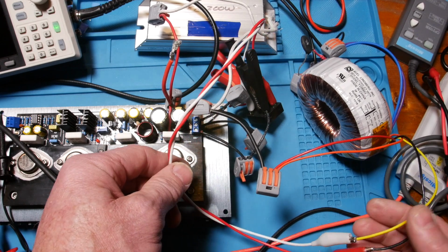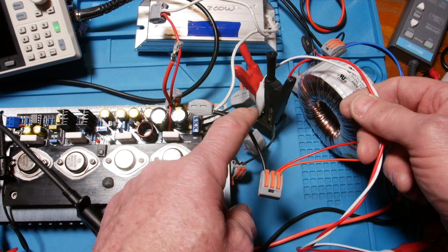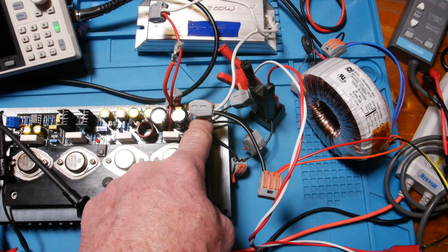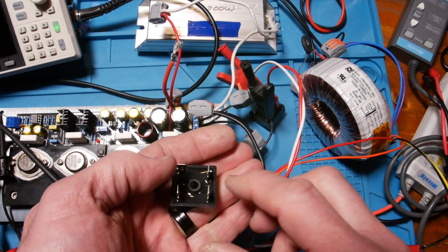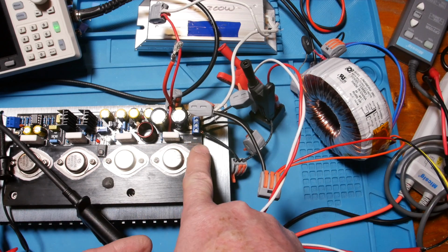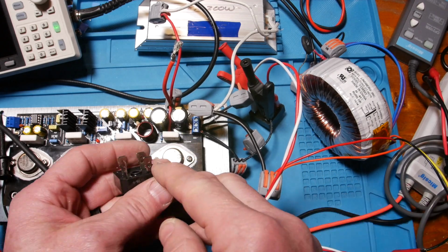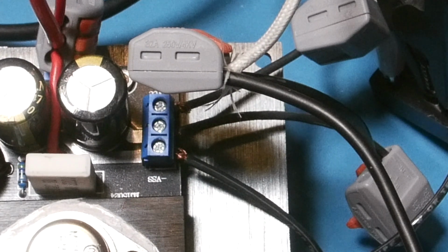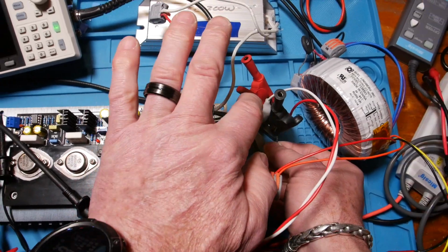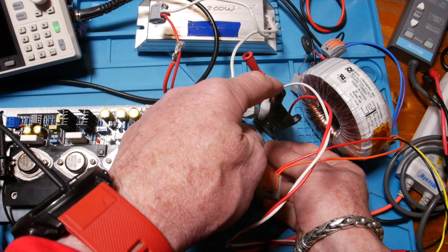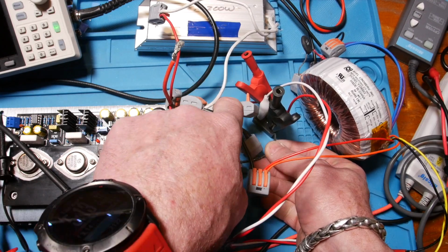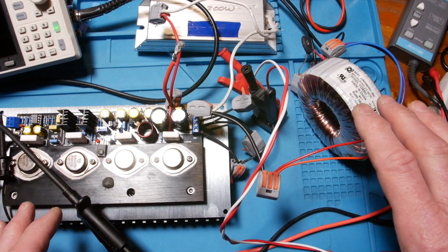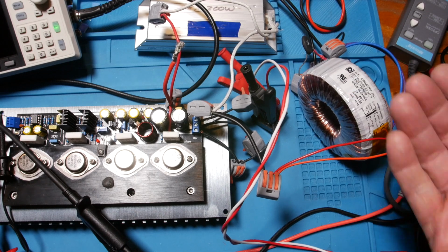This red and white wire coming from the transformer is going to go down to our AC. Okay, the center part's going right to the ground. So then the plus terminal off of this guy would go to the plus terminal up here, which is this one. And the minus terminal will come up and go to the minus terminal here. Okay, so and then all I'm doing is I've got these wires in, and then I've got the red and black one down here just clipped on with these two things. Like I said, this is super temporary just to test out this transformer, see if it's going to work for us.